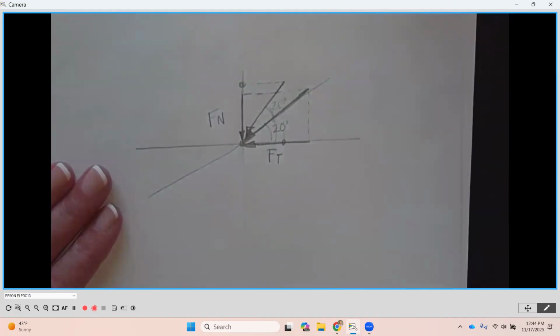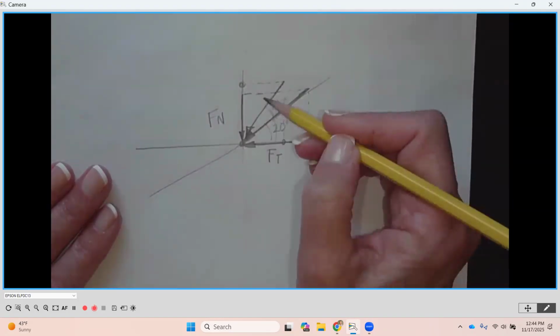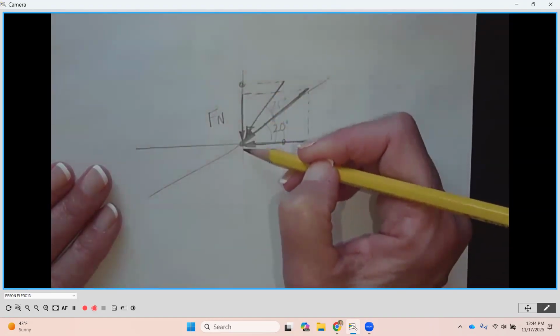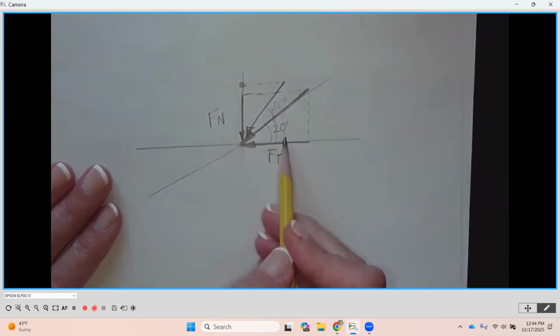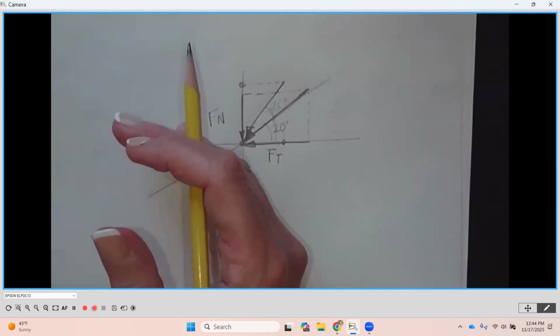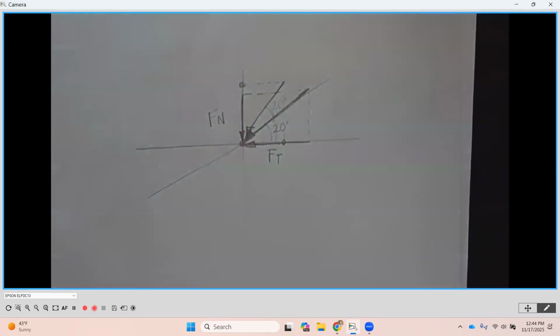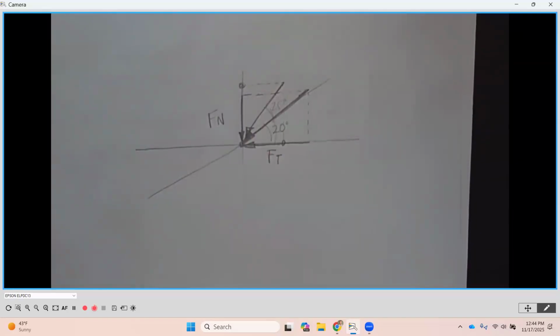So that's why if I know I have large forces coming in, I want to push as much of that Y component down towards the center of the gear where there's more material, and minimize the amount of tangential force that would impact that tooth when they hit each other, so it doesn't bend it over or shear it off. So 25-degree pressure angles are going to be for applications where we're going to see higher forces.